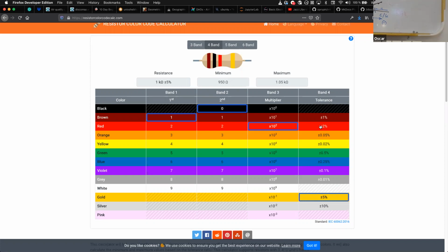It's like we have the LED, but in parallel, so there's actually no voltage. Right now, they are connected. So usually you use a resistance on the negative. That should work now, but probably we either have a problem with the cable that is on or with the LED.